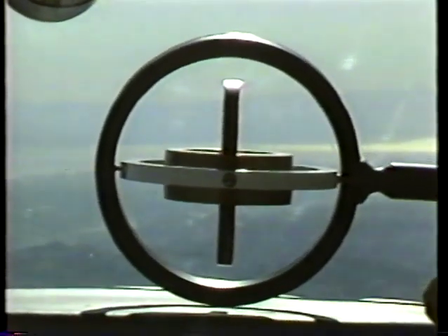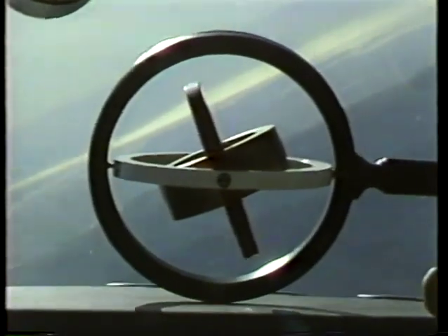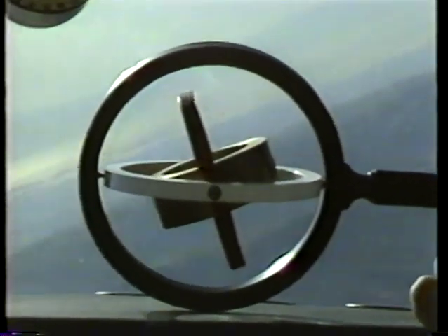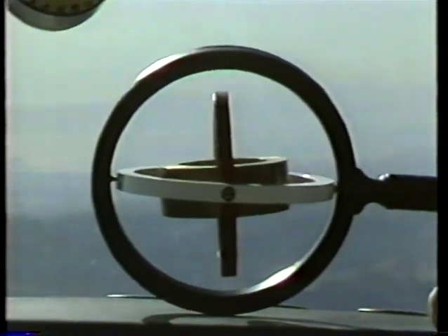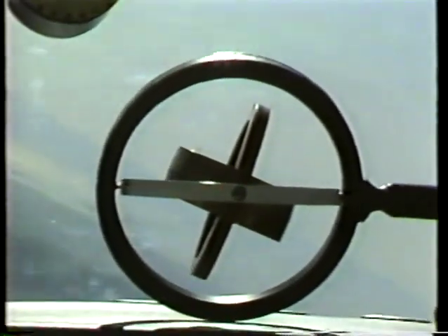space and precession. Rigidity in space is the resistance of the spinning mass to being moved or displaced from its plane of motion. Once set in motion, the gyro tends to maintain its orientation in space, regardless of the movement of its base or point of attachment to a moving object. Mounting the gyroscope in gimbals that can be attached to a base such as an airplane allows the gyroscope to remain rigid in space as the airplane moves around it.